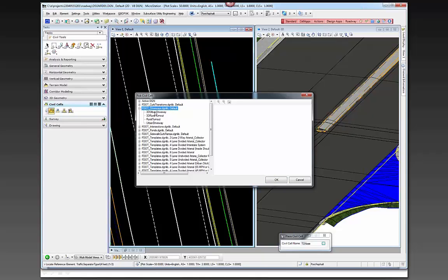There's an urban driveway that you can lay out just 2D. There's a rural driveway that you can lay out in 2D. And then you can modify these radiuses. In this case, you could modify the width of the urban driveway. You can modify the slope transitions here. Instead of being a 7-3 split, you could have a 6-4 split depending upon the width and according to the standards. You can change the sidewalk back distance.